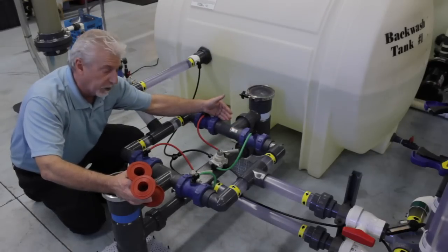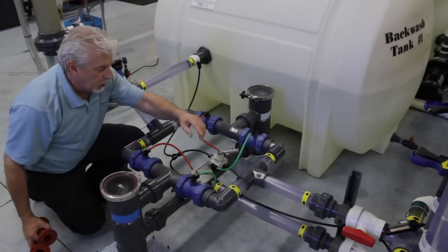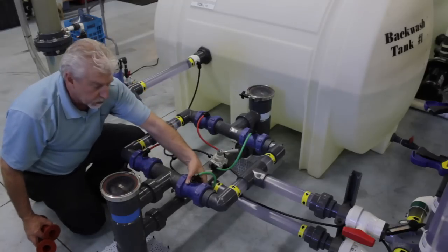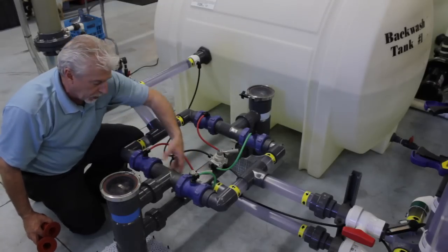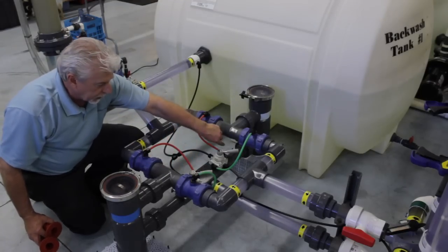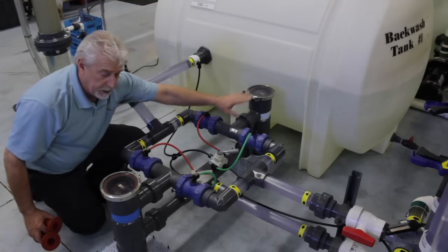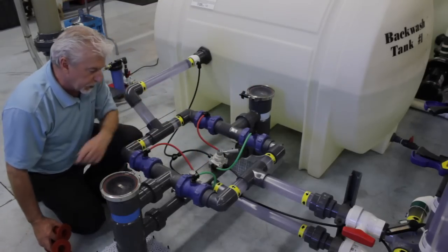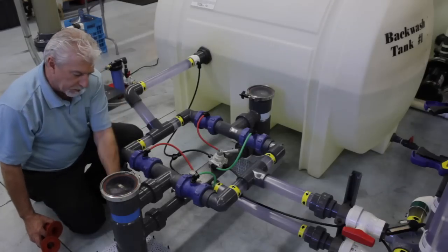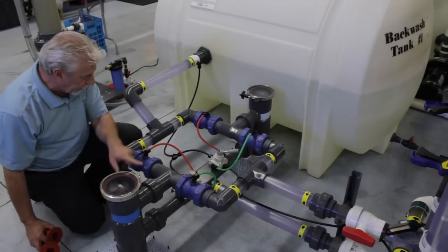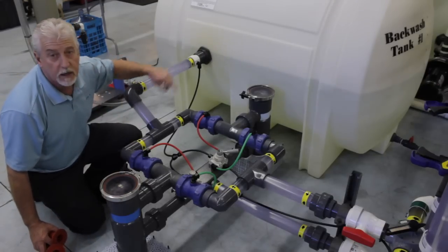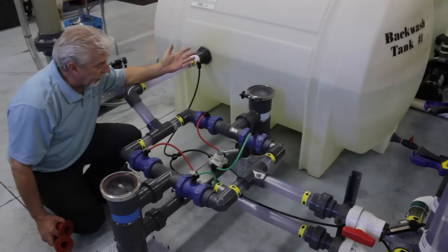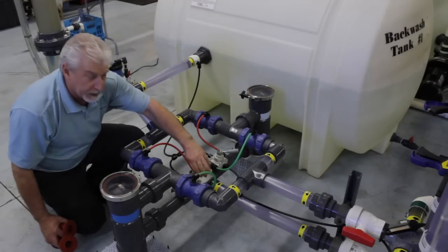Go to the next filter online, that would be this one. Now we're going to close the incoming water, the unfiltered, open the waste. It's going to take clean water from this guy, go through it backwards, backwash to waste. We do it with just the turn of a valve. Now we've got backflow through the second filter to the waste line. 10-15 seconds, it's radial flow, it's fast. Back online. Nothing to it.